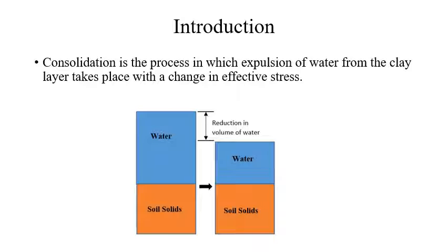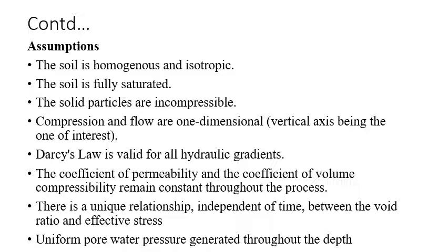Introduction. Consolidation is the process in which expulsion of pore water pressure from a clay layer takes place with the change in effective stress. Conventionally, the study of consolidation is carried out by the one-dimensional consolidation equation of Terzaghi. On application of the external load, an initial excess pore water pressure develops throughout the depth of the soil, and Terzaghi assumed that this initial excess pore water pressure is uniform throughout the depth.